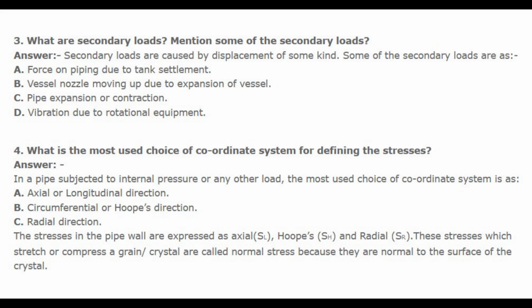Some of the secondary loads are: A. Force on piping due to tank settlement. B. Vessel nozzle moving up due to expansion of vessel. C. Pipe expansion or contraction. D. Vibration due to rotational equipment.